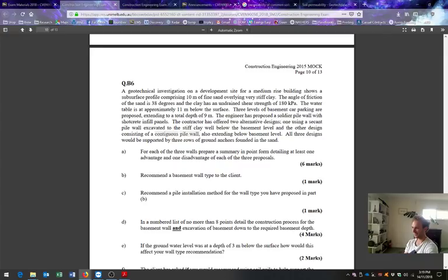Fraser, when calculating the structural capacity of piles, when do we assume partial reinforcement? Wow. For CFA, when the bottom can't be reinforced, yeah, that's a good example. Yeah, for sure. If we've got a CFA pile that's 35 metres deep, then we're going to have to pretty much assume it's partially reinforced. We're not going to get reinforcement to the bottom. But really, it's not something you just generally would assume. It would come back to the structural engineer a little bit, which I guess is probably you. So yeah, it's based on what's required from the pile. If you've got a lot of tension in the pile and it's rock socketed, you would have to do it fully reinforced. That's for sure.